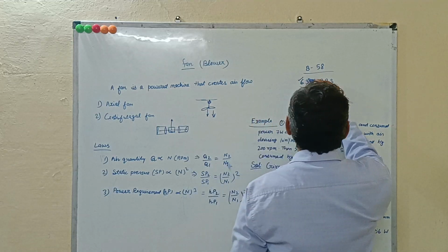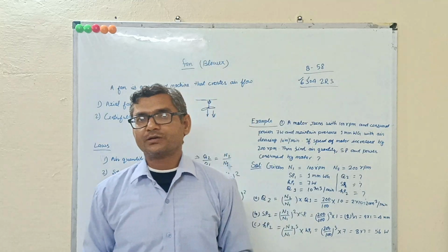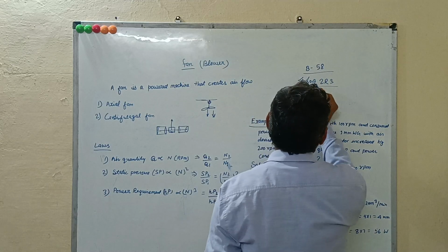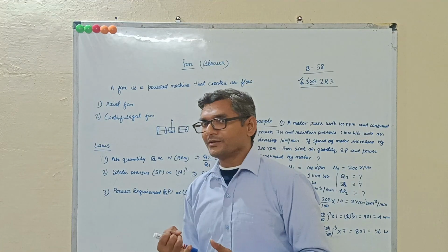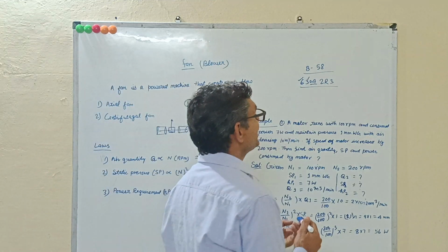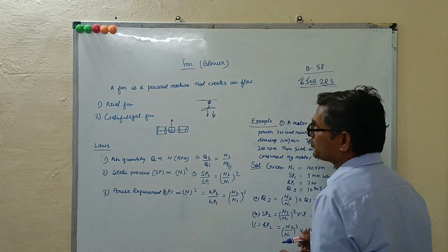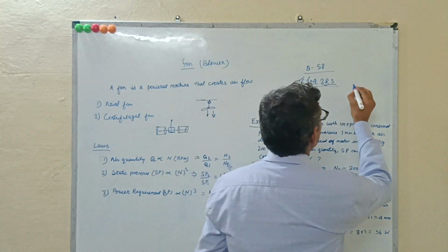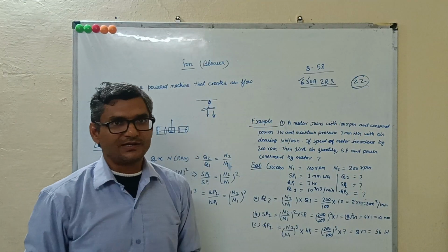Next, the second digit, I told, is the load on the bearing: medium load, high load, light load or heavy load. Okay. Next, the last two digits determine the shaft dia or bearing internal dia. Next is 2RS. 2RS means both sides are rubber shield bearing. Sometimes a bearing is written double Z. Double Z means metal shell bearing.